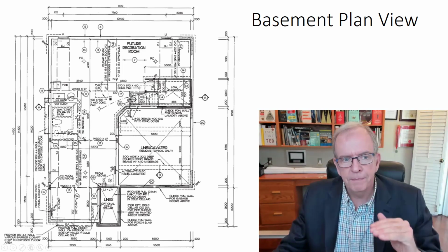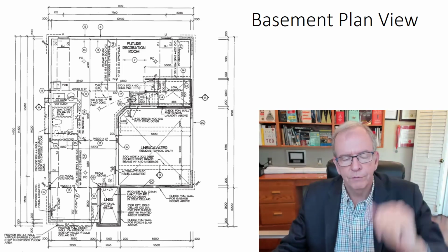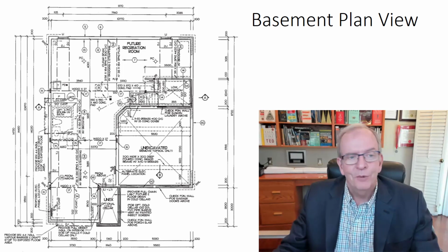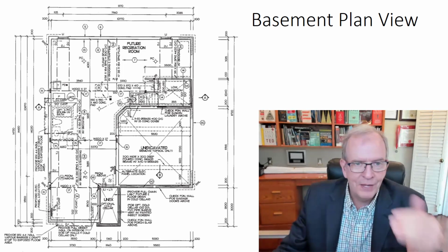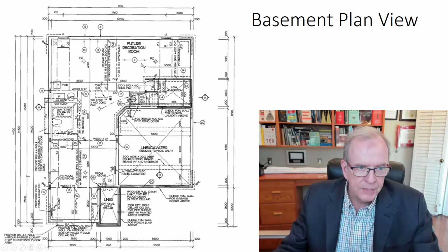Right? So you start in the basement, it shows the first floor joist. You start on the first floor, it shows you the second floor joist, and so on. And if you ever get disoriented about that when you're reading drawings, start in the basement. And you know, well, okay, if it's showing floor joists, it's not what I'm standing on, it's what's above me. Because typically in a basement slab, you're going to have a concrete slab floor in there.